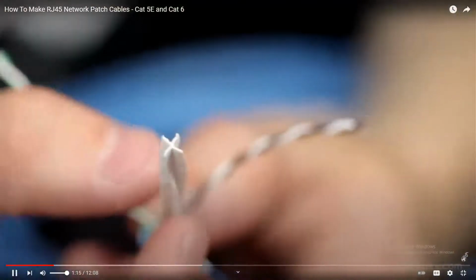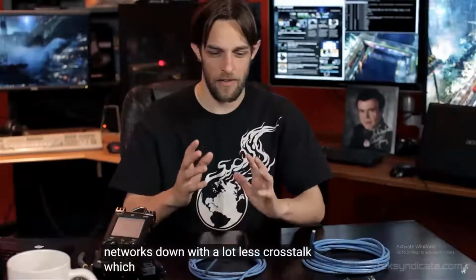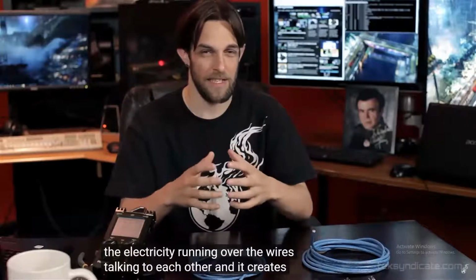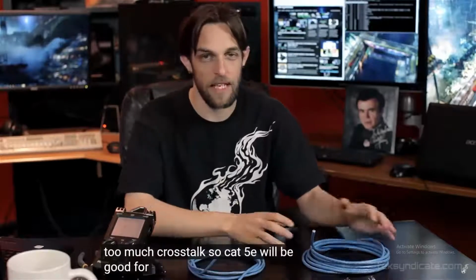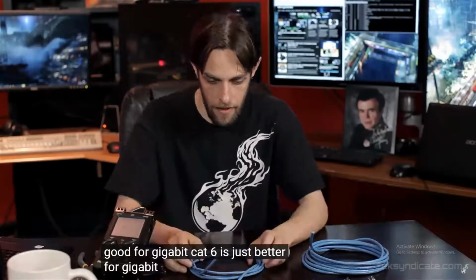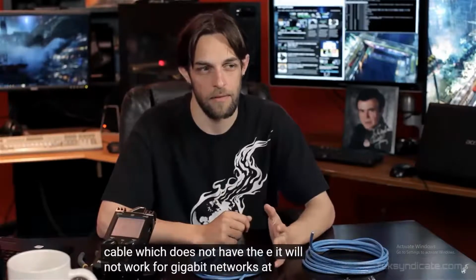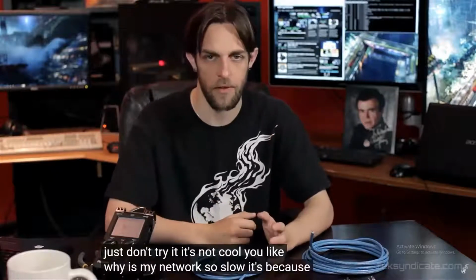People will always ask you what's the difference between Cat 5e and Cat 6. First and foremost, Cat 6 is a bigger cable. It is a higher standard of cable. It is able to shoot gigabit networks down with a lot less crosstalk, which is the noise made with the electricity running over the wires talking to each other, and it slows down your network if you've got too much crosstalk. So Cat 5e will be good for gigabit. Cat 6 is just better for gigabit networks. If you find Cat 5 cable, which does not have the E, it will not work for gigabit networks at all. Just don't try it. It's not cool. You'll be like, why is my network so slow? It's because you're not using good enough cable.